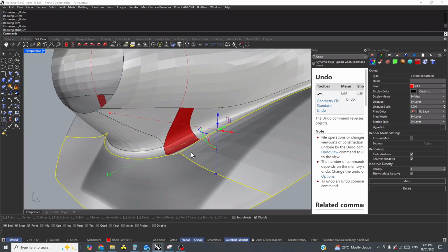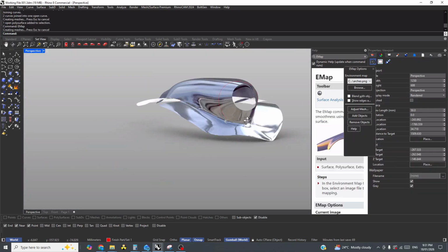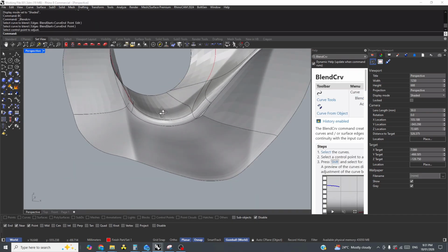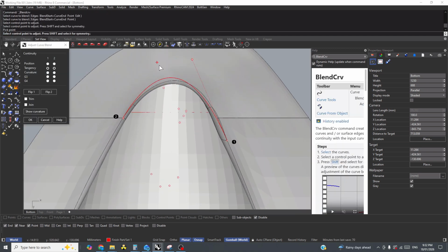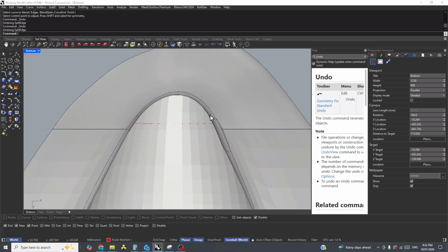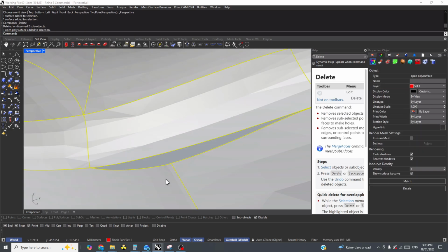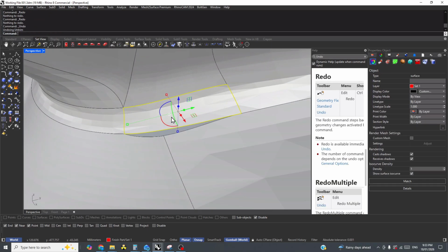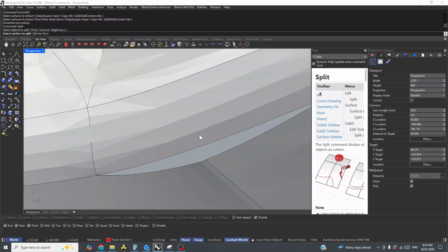So getting desperate here to try and create a transition, as you can tell. And at this point in a project, you've just got to ask yourself, how is this being manufactured? Is a mold being CNC cut for it? Because if it was, the person who's sanding the tooling would sand that out. Here, it being a composite part, it's a tooling board or an MDF mold. If it was an aluminium mold or a steel mold, that would be a different story. Or a 3D print, you could sand that out of a 3D print.